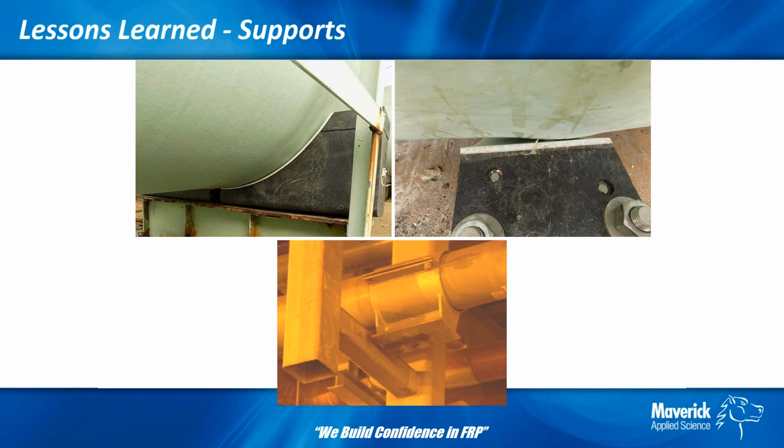And if you look at the left-hand picture in the upper section, you can see where they actually split the support to make room for the pipe joint, because the pipe joints were so big and oversized for the clamps that they had to split the support to spread it out just to fit the pipe in. Definitely not an ideal situation at all.